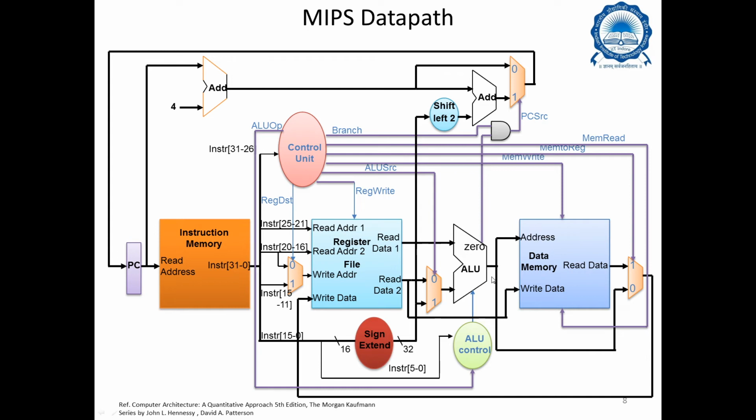It is also possible that we can totally bypass this and have the directly computed value of the ALU fed into another multiplexer, because we may not always be working on LW. So this could be a direct ALU output based on the computation of two registers in case of arithmetic operations.